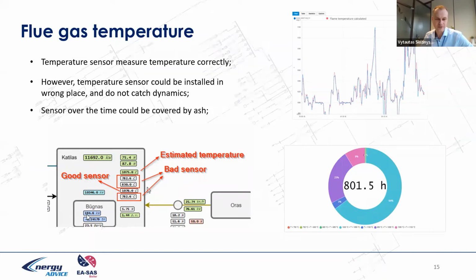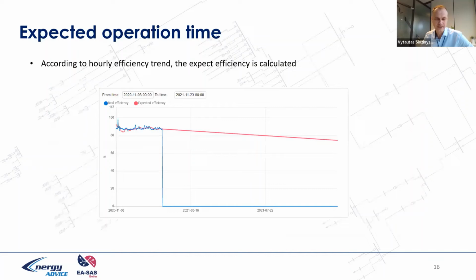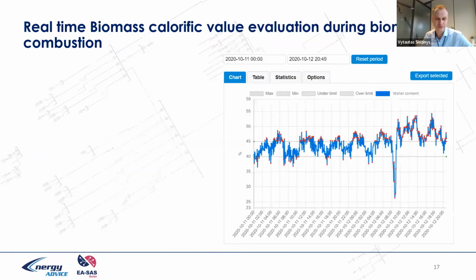Because of the fire tube erosion effect. If we have over temperature, we probably would face some erosion effects. If we have the trend and all conditions inside the boilers, we can extrapolate this and predict what would be in the future, how efficiency deteriorates, and when to make a decision to do something with this.